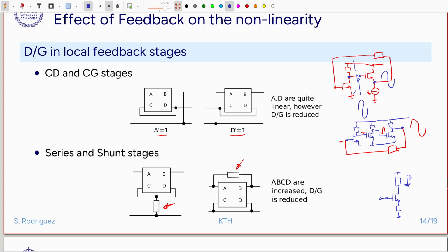When we have some current IDS at the output, the presence of the series resistance here already consumes some overhead voltage that is going to reduce the amount of voltage swing available at the drain to source of the transistor. So just its presence creates this voltage drop, and it already reduces the possibility of swinging around the drain to source. Just by that reduction, it is introducing some nonlinearity problem.